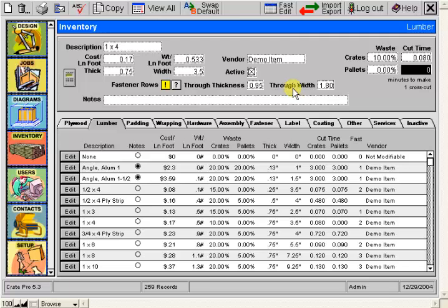What it will do is suggest to you how many fasteners to use at each junction where a stringer meets a deck board. This quantity of fasteners is determined by the surface area of that junction. After CratePro makes its reasonable and consistent recommendation, you can change the quantity and type of fasteners as you see fit. In this case, it'll simply provide you with a starting point.